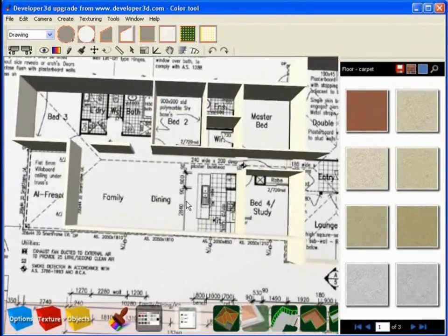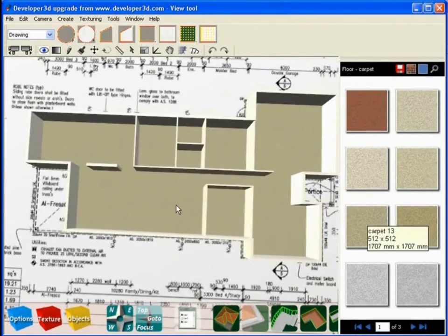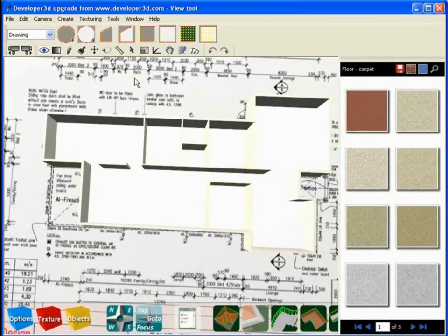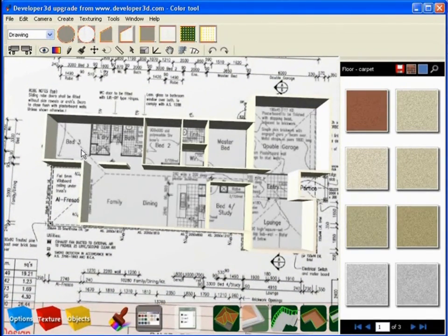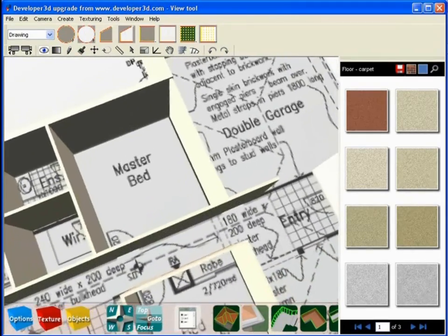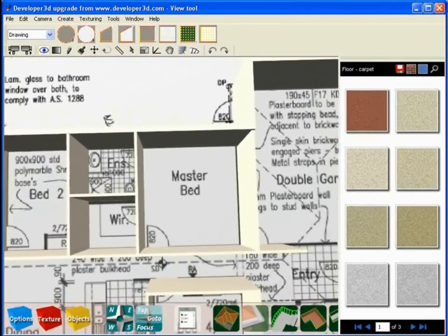So we actually have a floor that runs throughout our building, and in fact what we could do is go through the process of putting a material, for example, on this floor, but that material would then run throughout the entire length of our building. Now that might be a very practical discussion if what you're building is a commercial or in fact an industrial building, but as we're creating a model of a residential house here, it would be extremely unlikely that you would have the same floor finishes in every room of the house.